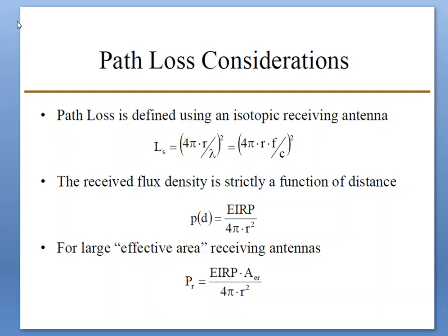The name conjures up an image of a purely geometric effect and fails to emphasize the requirement of gain as unity. A better choice of name would have been unity gain propagation loss. In a radio communication system, the path loss accounts for the largest loss in signal power. In satellite systems, the path loss of a C-band 6 GHz link to a synchronous altitude satellite is typically 200 dB.